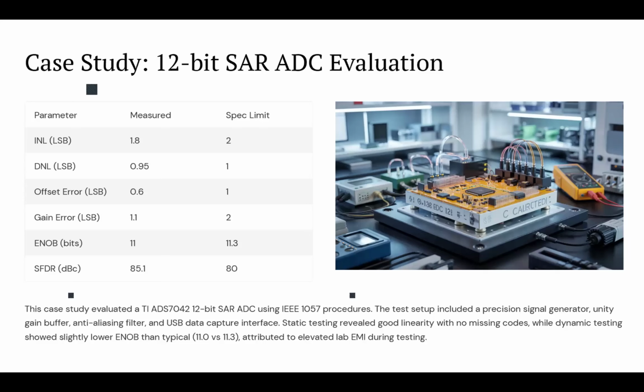Now, as we said, we have to make sure that the environmental conditions are also under control. One aspect is the temperature. Pay attention: not only do we have to control the temperature of the room, we already know any type of electrical or electronic circuit, when it runs, heats up because it has power loss in it. So not only the temperature of the testing environment is important, we need to make sure the temperature of the circuit is already stabilized, so the variation doesn't exist in the temperature in any way.